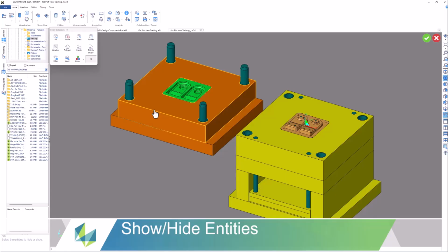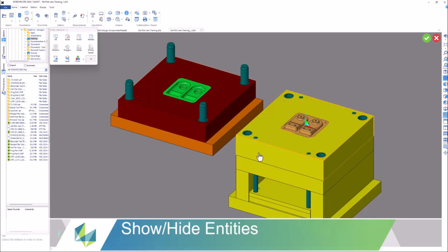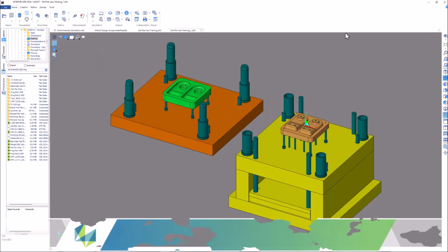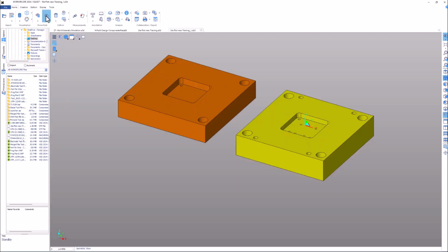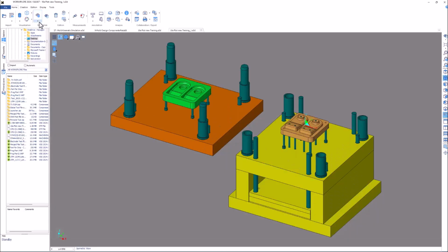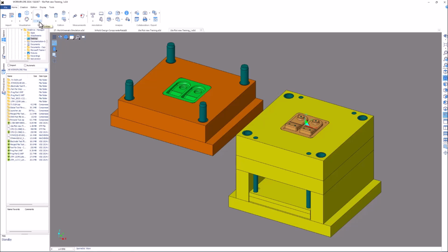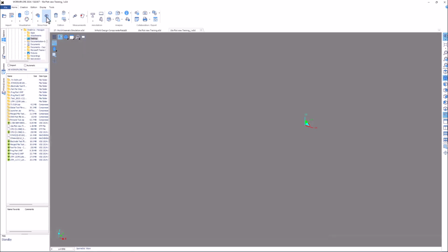And now we'll go into Show Hide. You can select individual entities, select individual file types, select individual colors, and you can show hide different items. You can flip the visibility for what you're hiding, what you're not, and then you can say Show All and pick specific areas, such as the model, so you can only see, let's say, 2D wireframe.